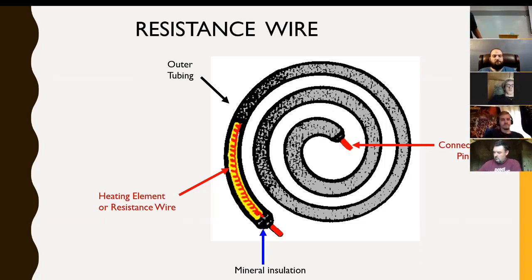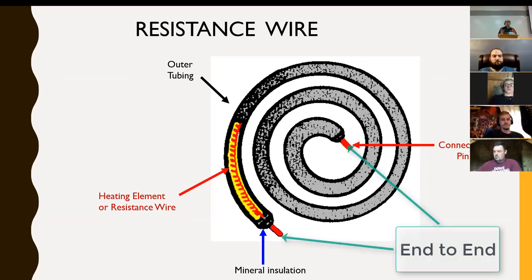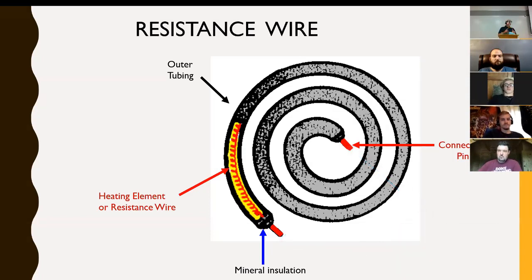And if you have a substance like a piece of wire, whatever that wire is made out of affects its resistance from end to end. And the longer that piece of wire is, obviously that's going to increase the resistance as well. And the other aspect is the circular diameter, the cross-sectional area. The bigger around a substance is, or a conductor, then the lower its resistance.